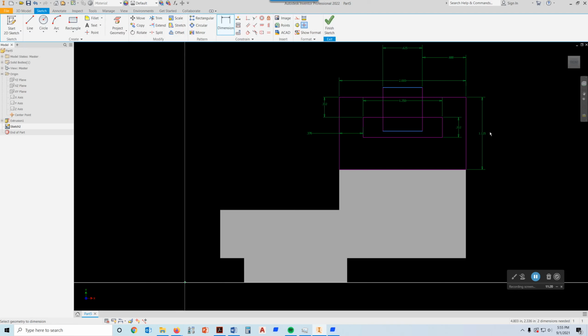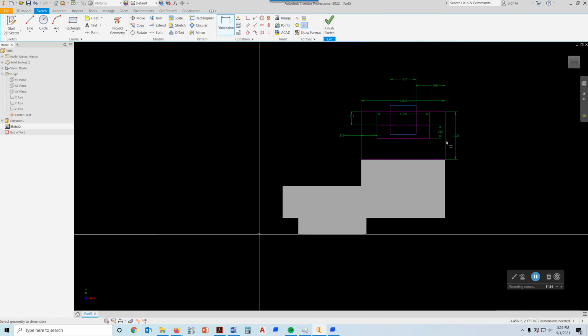You know, you can always clean your sketch up just by coming in here. Actually, you have to press escape, and then you can drag your dimensions out and drag them all off of the part if you want to. And it's not a bad idea to clean everything up. And I usually put longer dimensions outside of shorter dimensions. As you know, that's kind of our thing here.